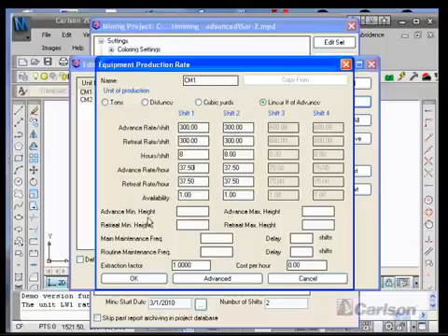The advanced minimum mining height and the retreat minimum mining height mean that if you have a piece of equipment that's thinner than the coal seam, you can take additional rock to get the clearance you need, and it will be calculated automatically if you put a minimum mining height in there. If you have a maximum mining height, then the program will automatically leave additional coal that cannot be reached.